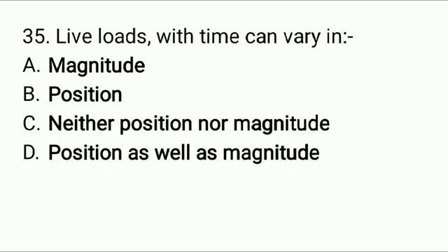Next question. Live loads with time can vary in. So what are live loads? Live loads are different for different buildings and structures, right? They keep changing from time to time. Even on some structures they vary in position as well as in magnitude. What are examples? Movable partitions, dust loads, furniture weight, etc. So live loads with time can vary in position as well as magnitude both. So our answer will be D.